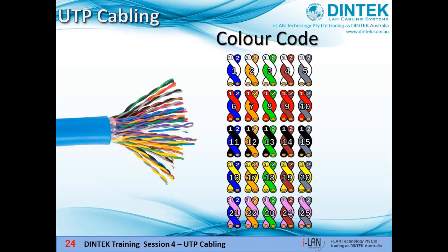It takes a pair of wires to make a circuit, but how do we tell them apart if we want to put multiple pairs of wires in one cable? The solution is we colour code them. The colour code we came up with uses 5 different colours for the B legs: blue, orange, green, brown and grey, which a lot of people call slate.